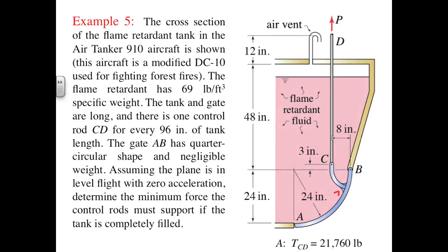I will assume this capability exists so that the pressure at B is based on a depth of 5 feet instead of 4 feet. The other thing to note are the little triangular icons between the curved pieces between C and AB. These are intended to indicate that the curved pieces are welded together. This is a rigid connection, so that the gray ABC piece is to be taken as a single rigid body. Let's now take a look at the solution.